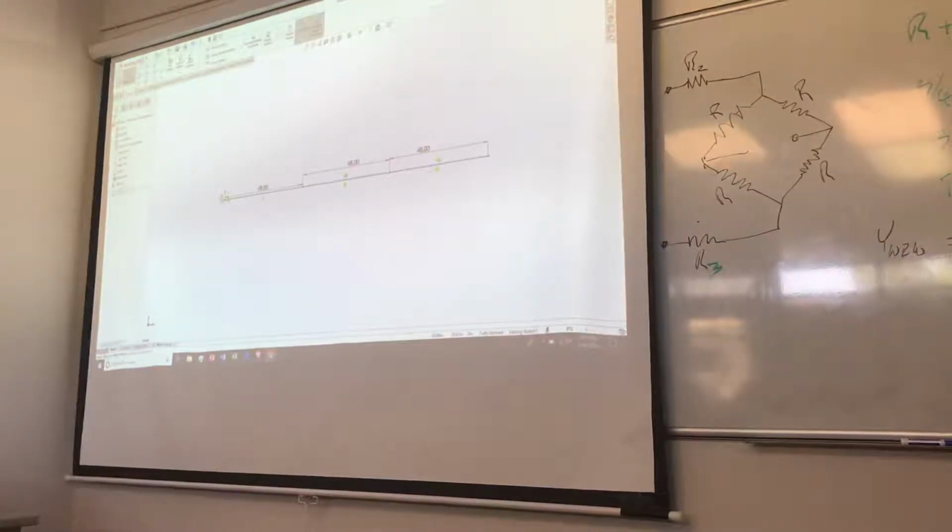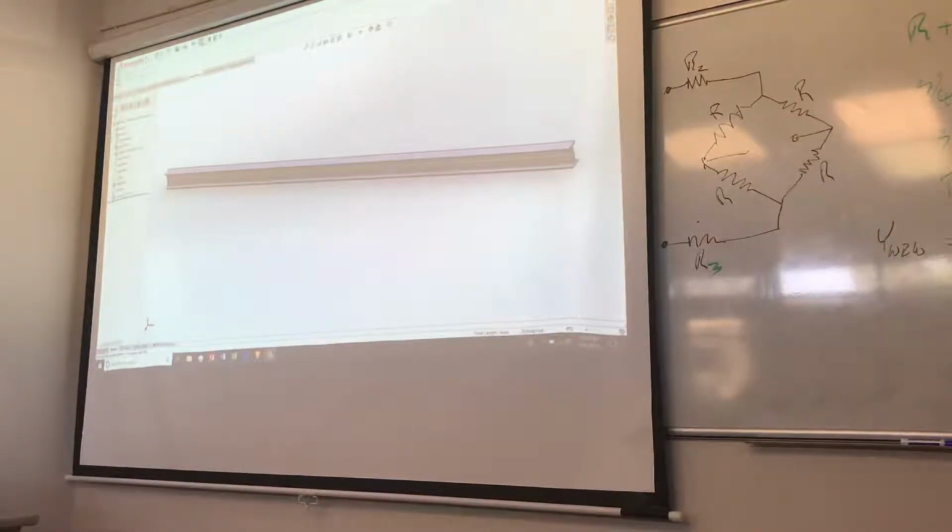Okay. Then I get out of the sketch, and then I have to go in and edit this guy, that's this one, and in the group down here, the path segments, I've got to click on these other ones. So in this path segment in your group, where you're defining one of those, you have to pick other segments. And so now I've got 3 segments. And I can say, okay. And I have a beam that's now the same length, but it's broken up into 3 chunks. We buying that?